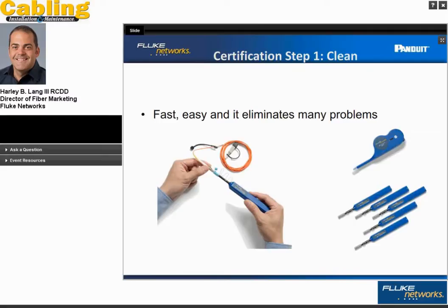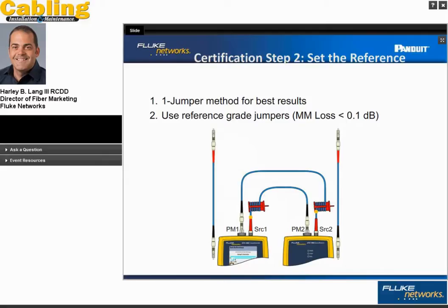But I want to remind the audience that the first part of all testing is cleaning. Without clean connectors, testing can be less productive than you'd like it to be, and accuracy can be compromised. So that's why I have cleaning here on the very first slide of certification.